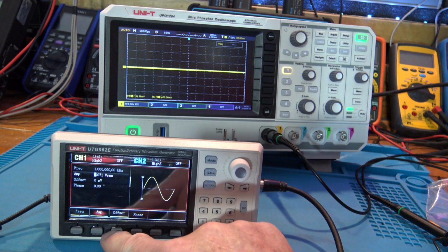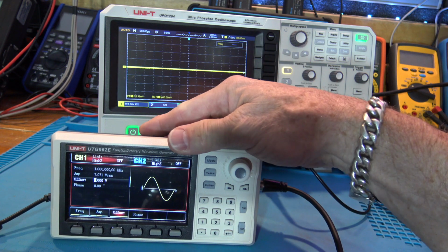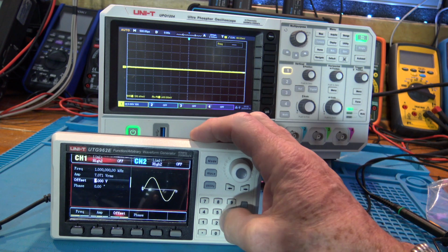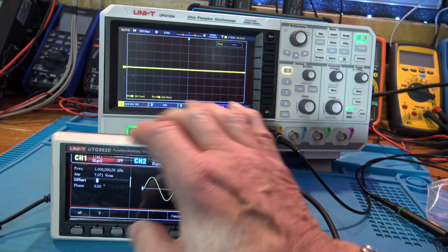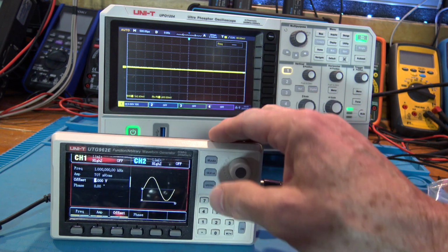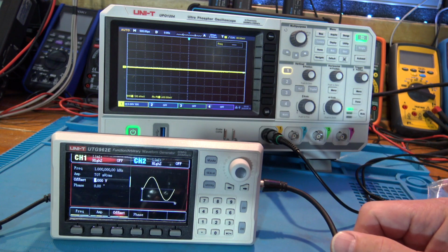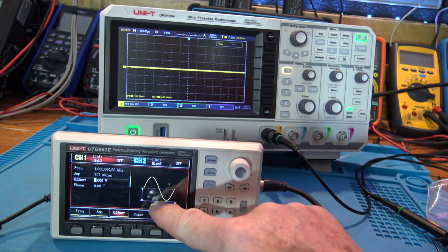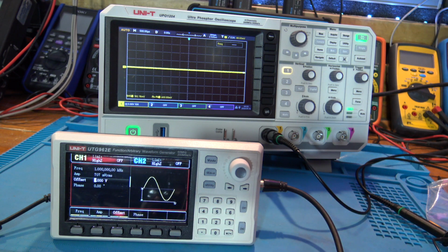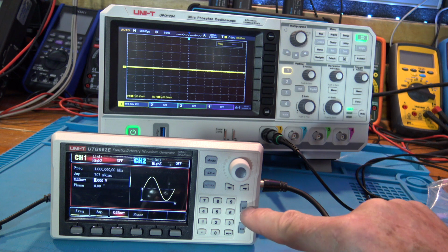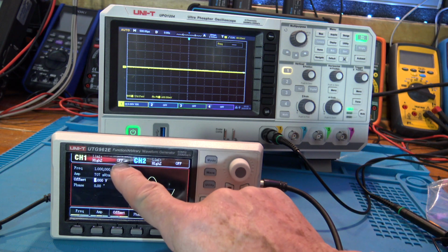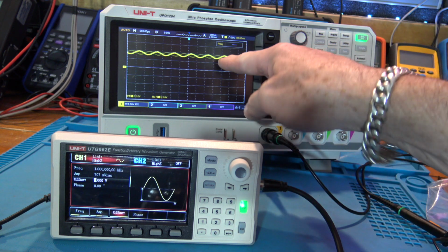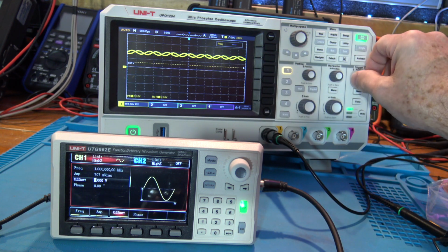All right, and then offset, I can put a DC offset there, and I can just start pushing any number. Let's say if I want to say 9 volts, millivolts and volts, and it gives me 9 volts offset, okay? And it shows you what it looks like here. So now my sine wave is going to be up here, okay? But I don't see anything on the scope because the output's off right here. So I can push this button right here and it turns it on. And there's my waveform. I can bring my trigger up.